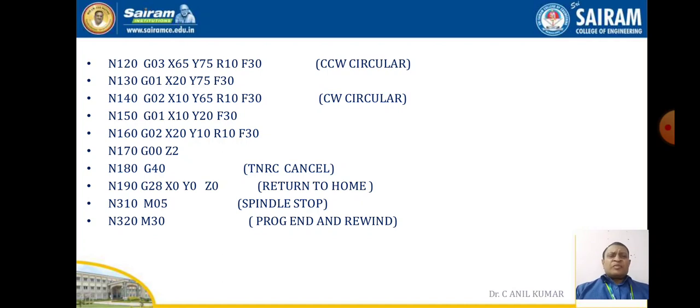See, this is a program which is used to get the component. Now here in this case, the feed rate as well as the spindle speed can be varied depending upon the type of contour we are fabricating or manufacturing. If we are going for the inside radius or internal radius, then the feed rate can be given as a smaller one.